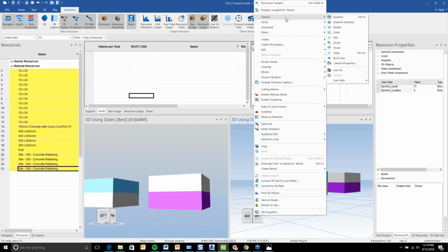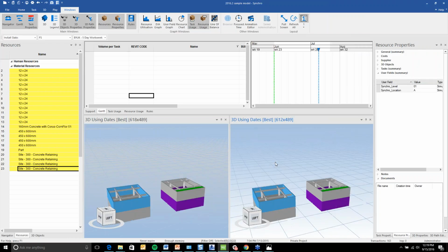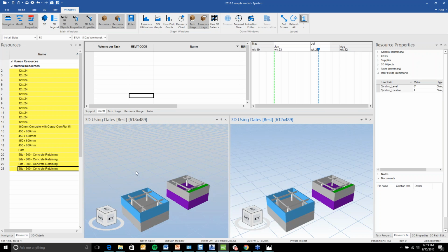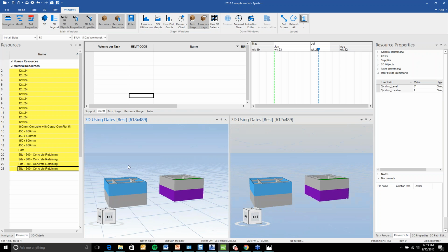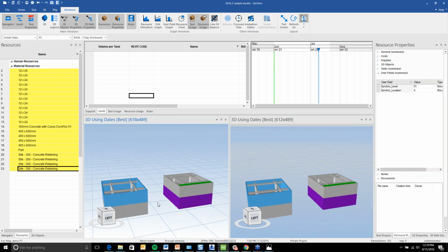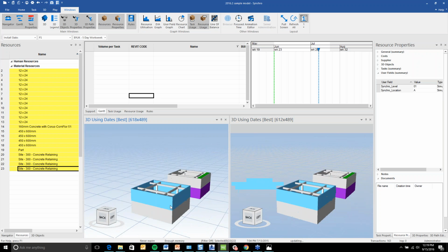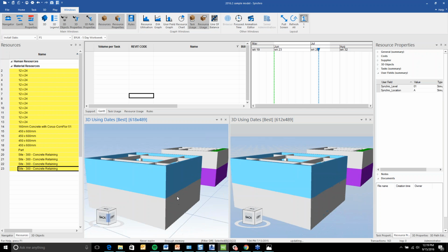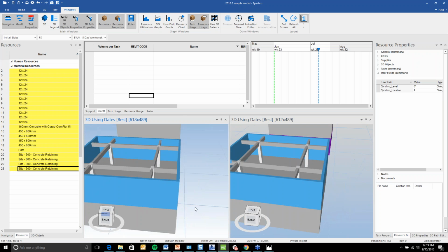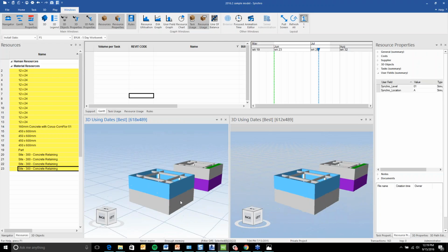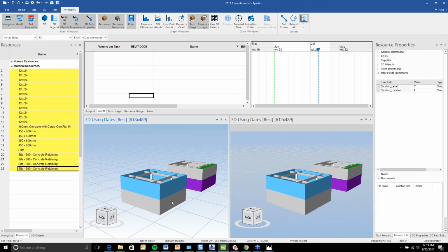But now with the camera option, we have this option to link our views. And once you link a view, it doesn't matter which one you move the cursor into, they will both orbit, zoom, and pan at the exact same rate. So it's a nice way to set up multiple views in which you just need to move the camera once and they all update.